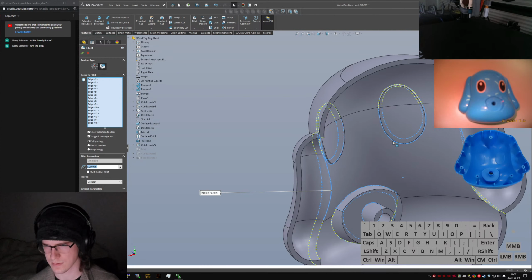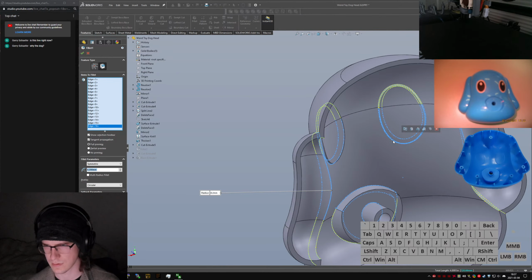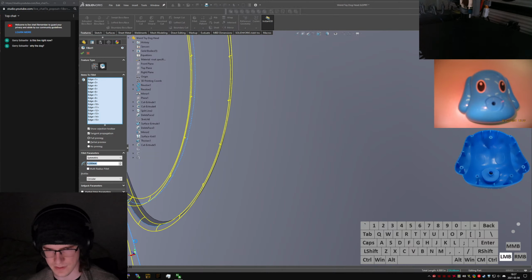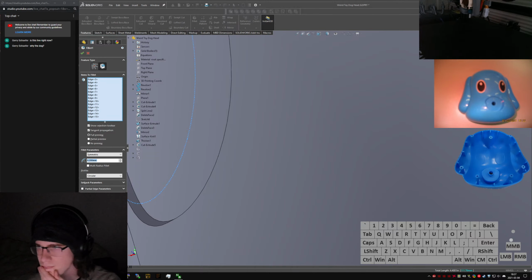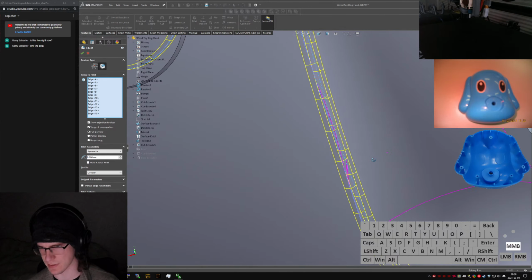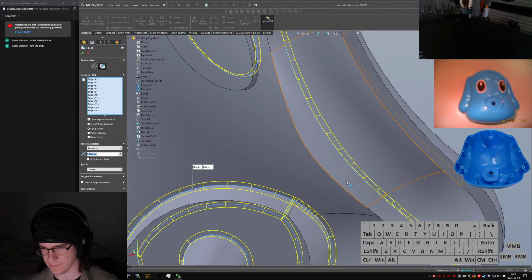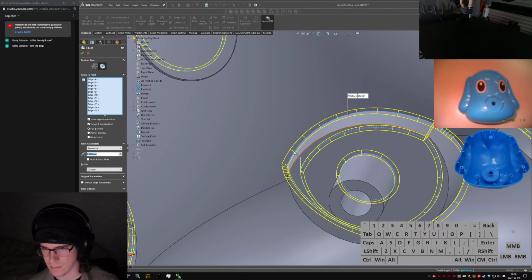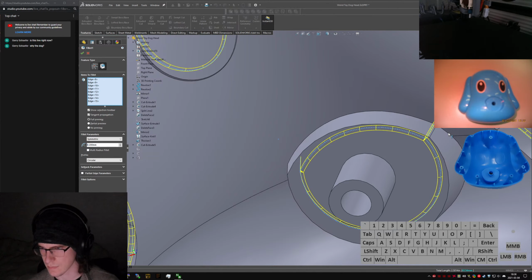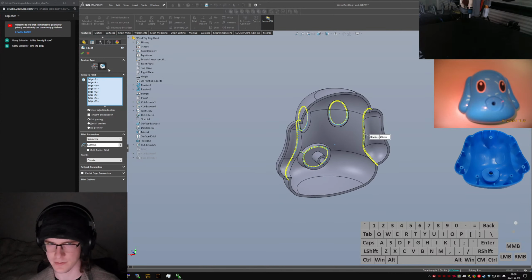Oh, goodness. Hang on. I got to zoom in, and I got to manually remove all these fillets. Because when they're on the inside first, where I'm still creating features, it's going to break things. Okay, now those fillets are only on the outside, which is fine.